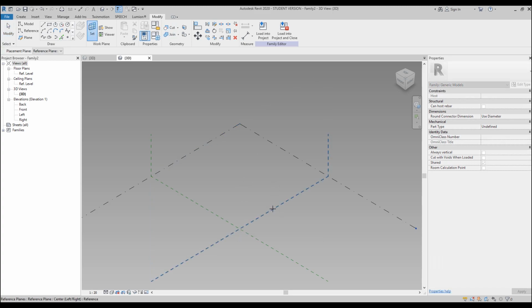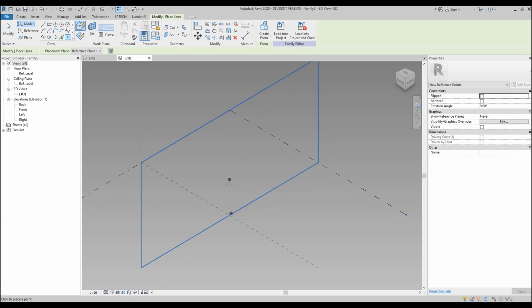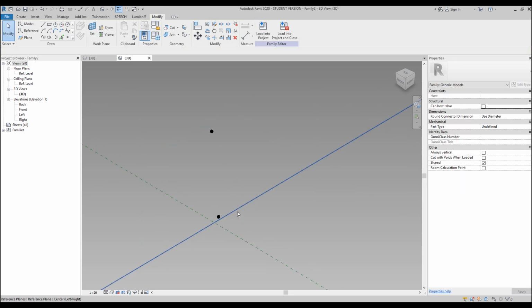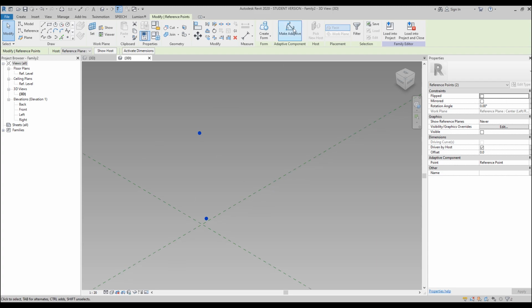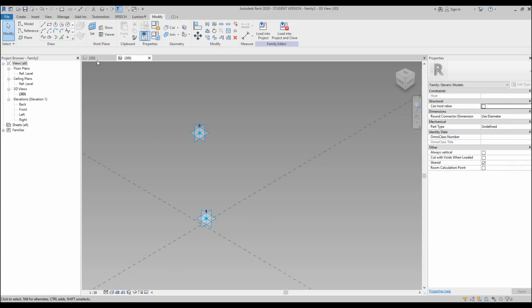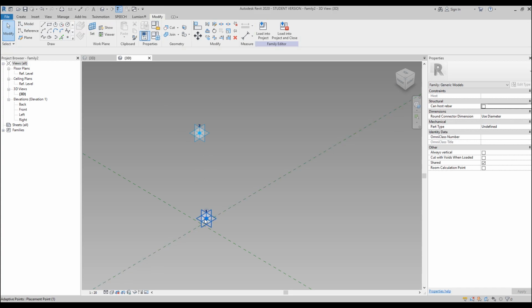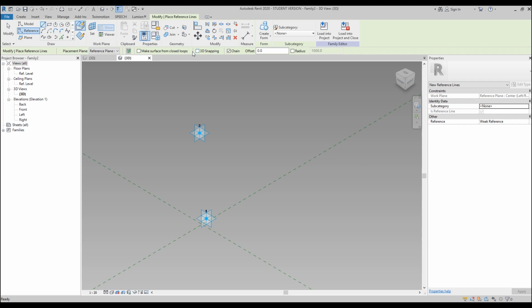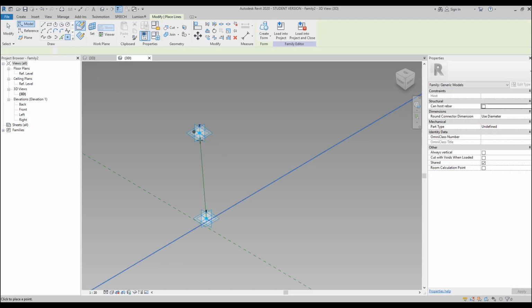Let's use the set this working plane. Let's place 1 point and a second point. The distance between the two of them doesn't matter. Let's make it adaptive one, point 1, point 2, and we need one more extra point, but not right now, because we need to create the line between this point and that. Let's do that. Go to the reference, find here the line, don't forget about the 3D snapping, and snap on the one place and the second place. And now you can place this point.